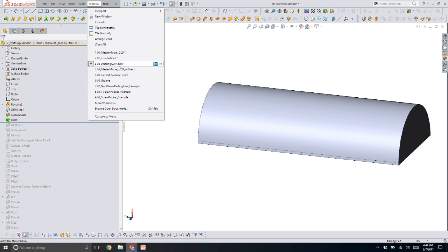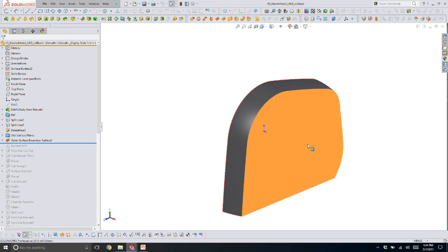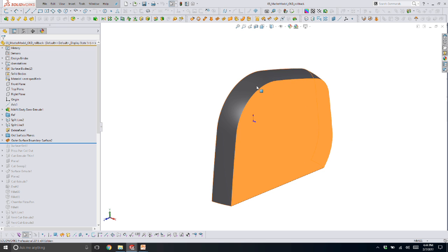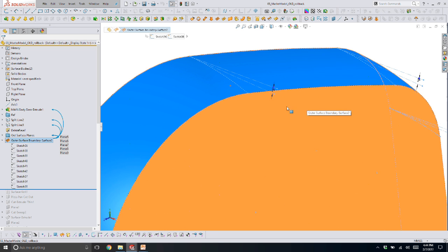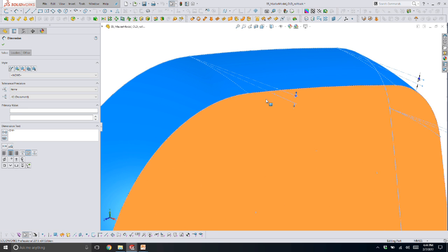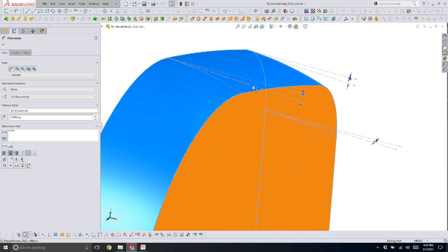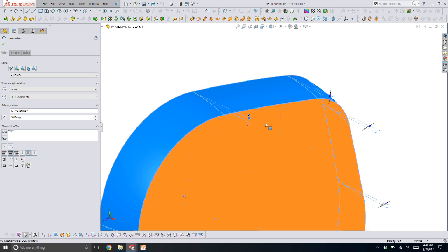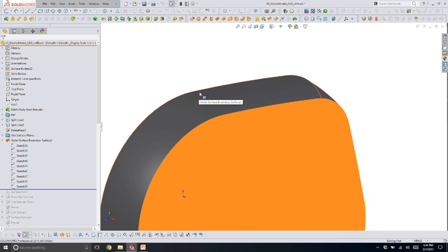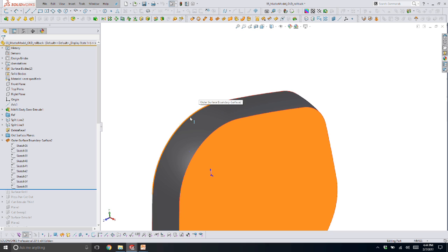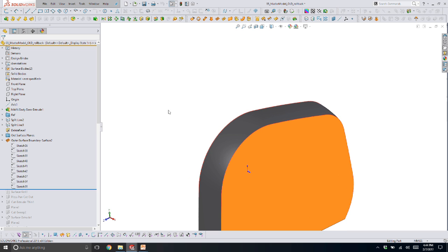So, going on to our next example. If we look at his original surface versus what we corrected it to, what he did was set all of his arcs that make this crown face to be tangent to center lines with the 3 degree draft angle. So all of his profiles are good. Every time there's a profile in his loft or boundary surface, they're very similar. He has the correct 3.5 degrees draft.